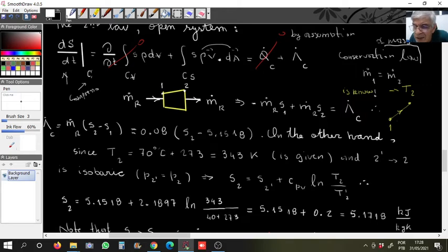Now T1 is given. Do you remember? Look, I have a curve over here. This is only vapor in this line here. Do you remember state 1 here? It comes from the evaporator. This is 1, only vapor. This is from the table. Also, do you remember the saturated temperature at T1 is equal to minus 5 degrees centigrade, because it's in the evaporator. The evaporator is for 4 to 1. So the temperature at 1, I know.